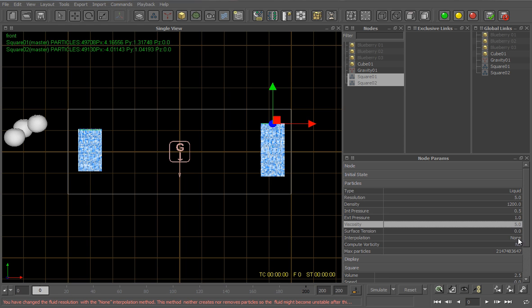5 is even better. The last parameter is called surface tension, and much better suited for our purposes. With higher values, the fluid's tendency to form drops and filaments increases, and this is exactly what we need. To get really nice drops, the value shouldn't be too small, and we try 200 here.